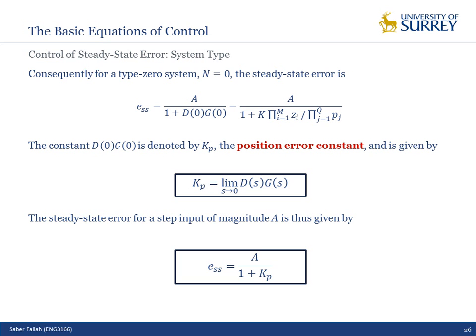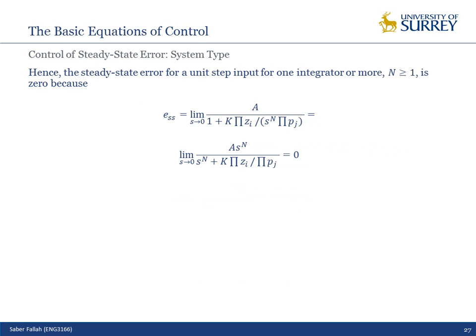How can we judge that we need the PI controller or PD controller or just an integrator controller? Correct? So as you see here, by adding an integrator controller, we increase the type of the system. By increasing the type of the system, we improve the steady state error of the system. Okay.